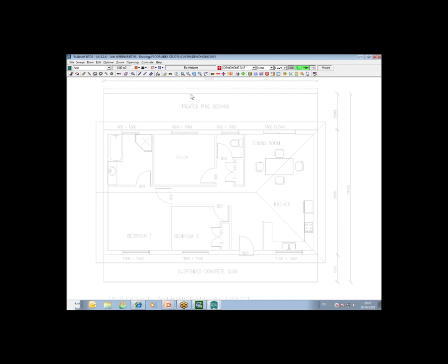Then moving from there over onto the right hand side of the status bar, there are a number of options here with regard to the type of return. As in Buildsoft, you can have an exact return, round up, round down, round nearest. I would recommend when you're using the BTOS module to have that automatically selected to exact. Bear in mind that these results will be returned into a calculation sheet in Buildsoft, and there may be a rounding applied in there as well. So it's best to return your results out of BTOS in an exact mode.